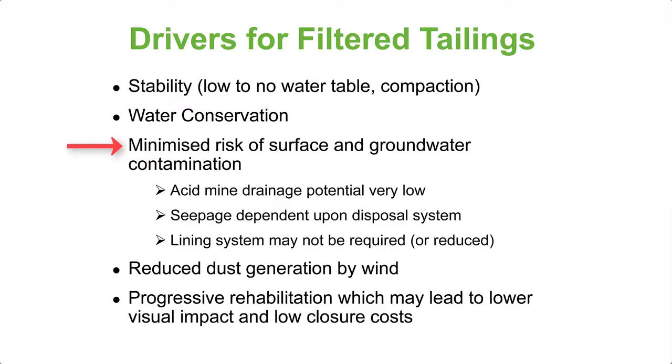And in particular, if your tailings has the potential to generate acid, the acid mine drainage potential becomes much lower. Seepage is much less, and depending on the type of tailings, depending on the area, you may or may not even need a lining system, which is quite common in certain areas and certain jurisdictions like South Africa, where that's becoming a requirement.